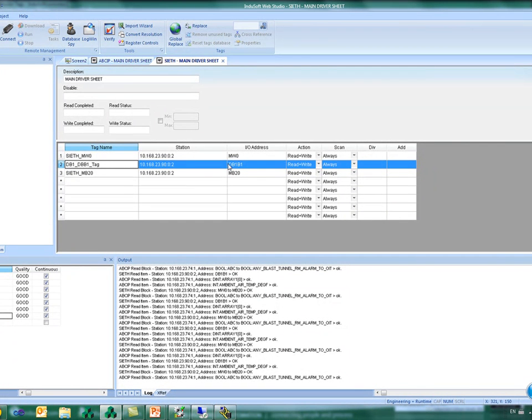Not quite. Try to keep the number of DBs used in the communication low. Let's say you have 3 or 4 DBs and use all the positions of these DBs. We can fit up to 1022 bytes for each DB communication. So the fewer the messages, the better the communication. Okay?